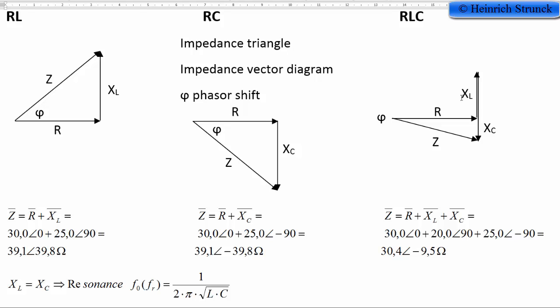We also could have that the reactance for the inductor and the reactance for the capacitor have the same length, then we can see that the impedance must be the same as the resistance, and we call that resonance.